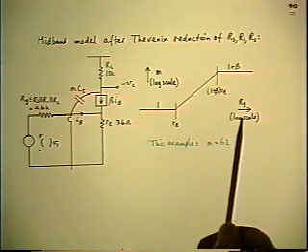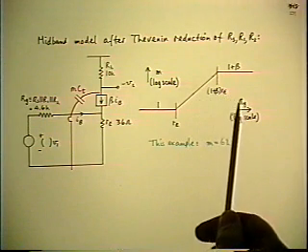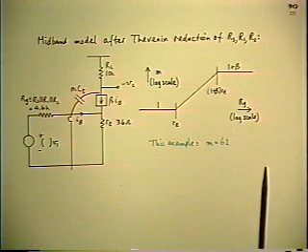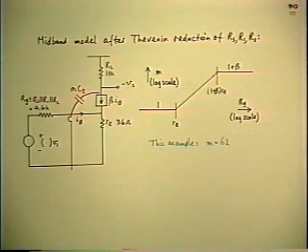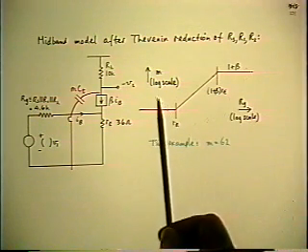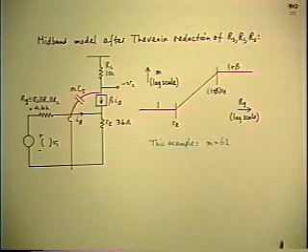I think what I'm hearing is you're saying the variable in this case is resistance, not frequency. In other words, the variable is a real variable, frequency is an imaginary variable, s equals j omega. So when you calculate the magnitude of the frequency response, you take the square root of the sum of the squares, root 1 plus omega squared. But this is a real function of a real variable. So it's simply 1 over 1 plus 1 at the corner, or 1 over 2, not root 2. So you get a 6 dB corner instead of a 3 dB corner.